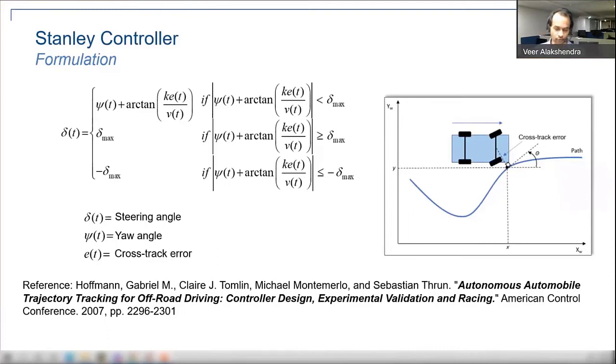So again, we're not going in depth into this. We have nice good papers available, but the summary is that, having a vehicle model and a reference track, we are implementing one driver which is based on the Stanley controller, which gives you the steering angle based on cross-track error. Okay.